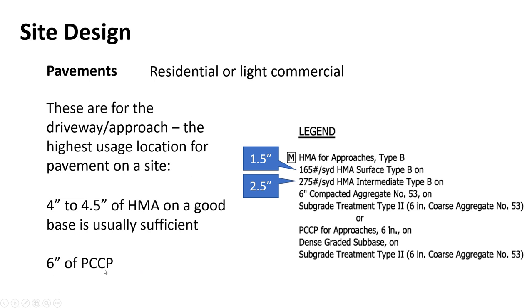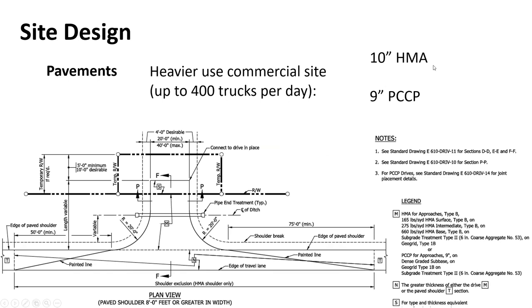And a lot of it is that if you've got that wire mesh in the middle, you want to have over 1.5 inches and probably more like 2 of cover, so that it keeps the chloride from seeping through and attacking it. These are the hard limits of what you can reasonably build and will hold together nicely under traffic. It's not by strength. Now this is getting into strength design, right? So you don't need as much concrete in this case. So great, but concrete's more expensive than asphalt almost always, especially right now. So you're gonna be better off with the 10 inches of HMA, right, for this.